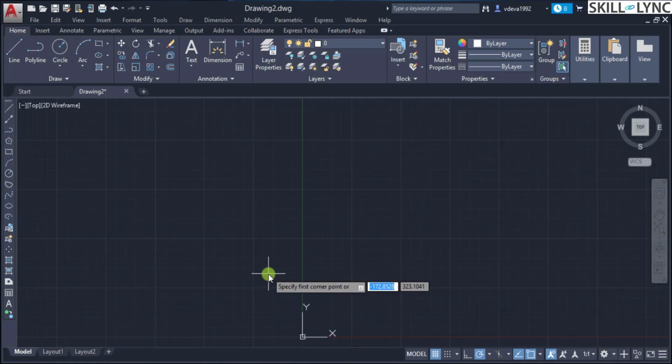So let us draw a rectangle, specifying the point as in here. Let us start with some random point. The width is going to be 400 mm and the height is going to be 200 mm. So with this rectangle plate, now we have constructed the rectangle, and the next task is to fillet these corners. One way of doing it is using the fillet command inside the rectangle command that we have seen earlier. We have to do that, but before that, let us try and draw the M8 holes that we intend to position. Towards that, we understand that we have to zoom into this page.